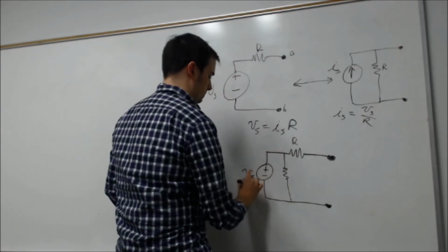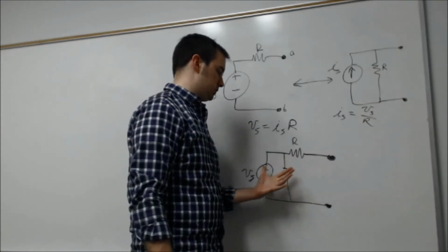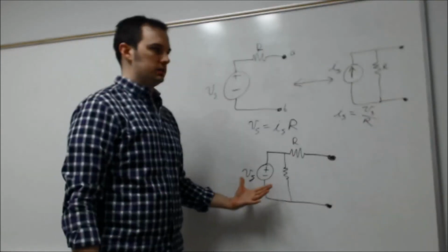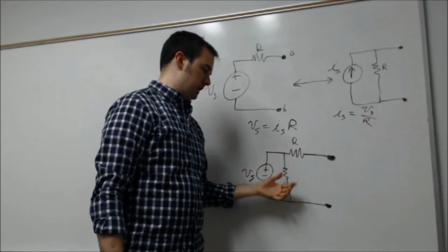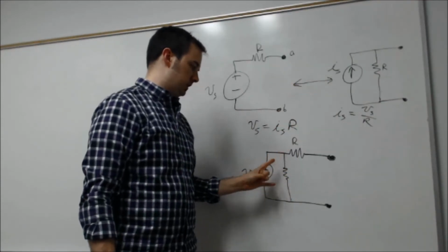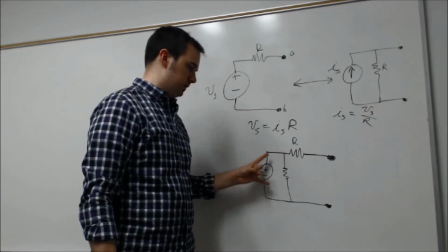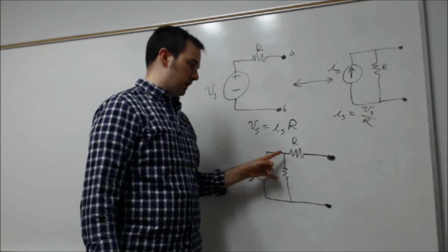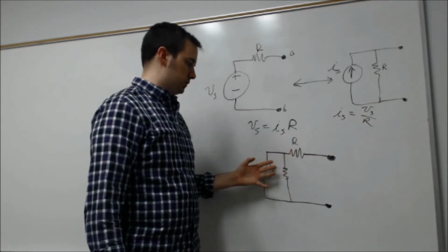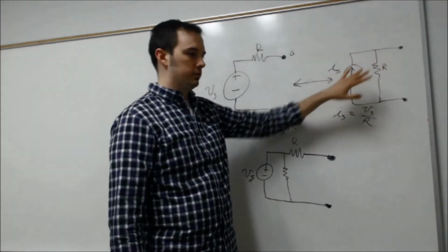Well, for all intents and purposes, and thinking about specifically what's happening at these nodes here, I can transform this in the exact same way as I'm doing with this version here, almost negating the impact of this. That's simply because this resistor is in parallel with this voltage source, so the voltage potential across it is the same, and therefore I can still do this transformation and simply go from what you see here directly into what you see over here.